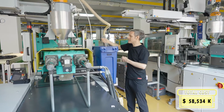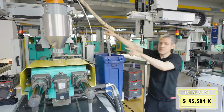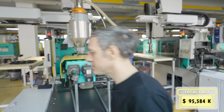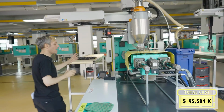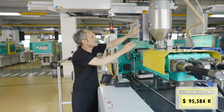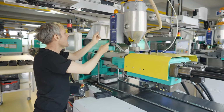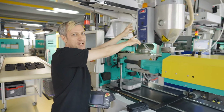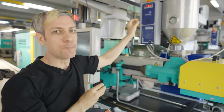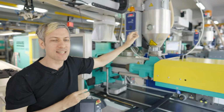So first, the plastic in this hopper is vacuumed up through this hose and goes into the hopper. Now the hopper pre-treats the plastic by first heating it, and this special jacket right here is a heating jacket that heats up all the plastic, and this device right here blows compressed air onto the plastic, and the thing that's unique about compressed air is that it's very dry.